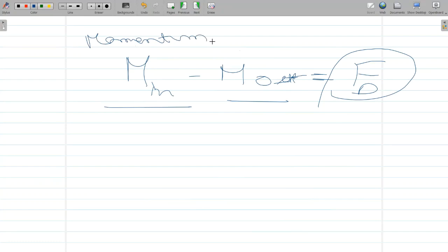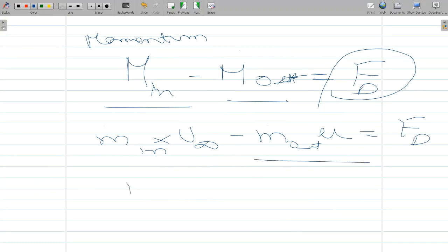All right. So the momentum that is coming in is nothing but the mass flow rate that is coming in times the velocity with which the flow is coming in. And the momentum going out is nothing but the mass flow rate going out times the velocity with which the flow is going out. The velocity is varying with space, so we would need to integrate accordingly. So let me look at the mass flow rate that is going out separately. The mass flow rate that is going out would need to be integrated as